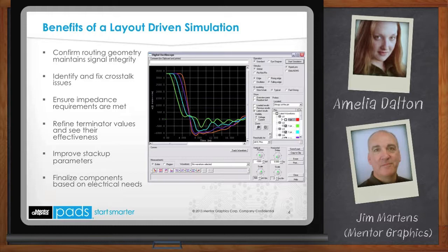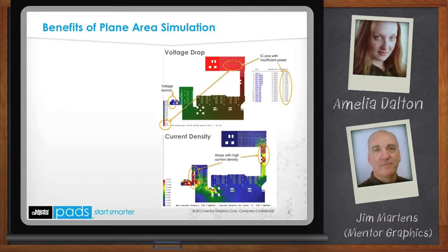You're right, it's not uncommon to have a split with 12 to 15 planes because of the power rails from today's components, which are designed for low power consumption. So fast feedback on plane design will increase productivity and quality without adding to your development schedule. After placement is finalized and planes are designed, but before routing, it's a good practice to check the power integrity of plane areas. After routing, run your power integrity checks again to confirm that newly added vias haven't introduced power issues.